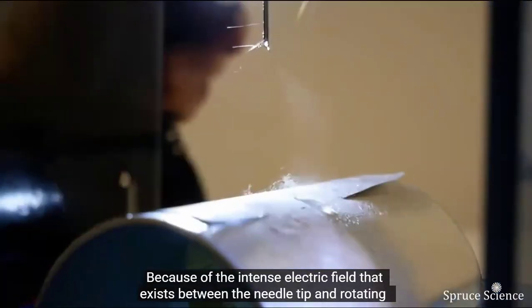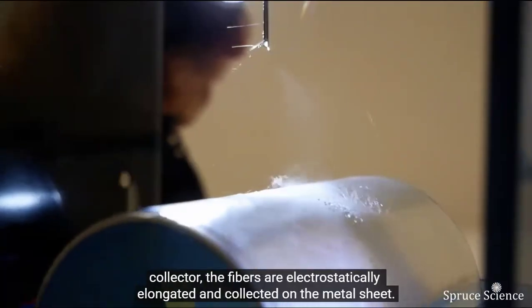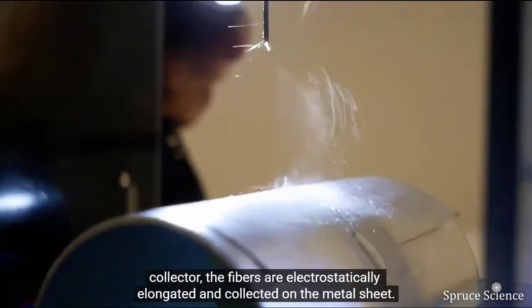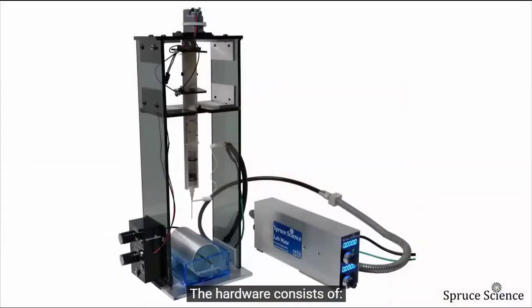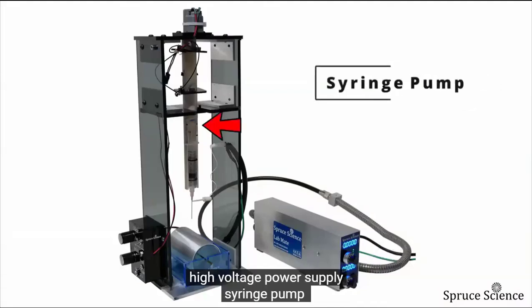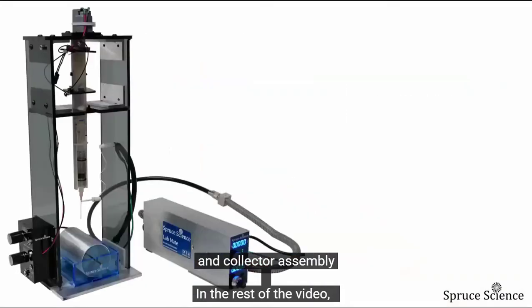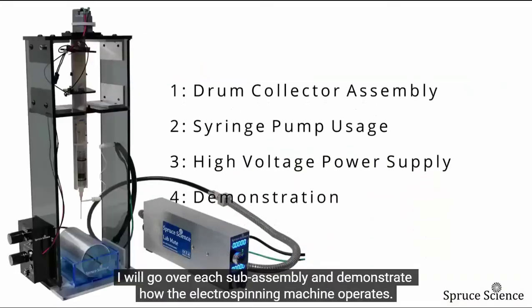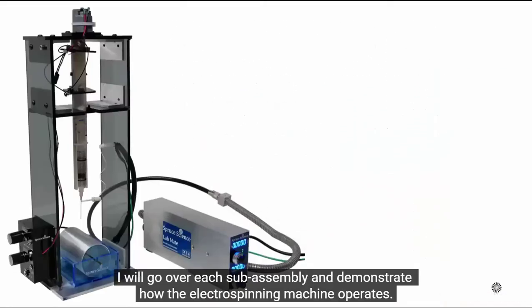Because of the intense electric field that exists between the needle tip and rotating collector, the fibers are electrostatically elongated and collected on the metal sheet. The apparatus used in the electrospinning process is shown here. The hardware consists of high voltage power supply, syringe pump, and collector assembly. In the rest of the video, I will go over each sub-assembly and demonstrate how the electrospinning machine operates.